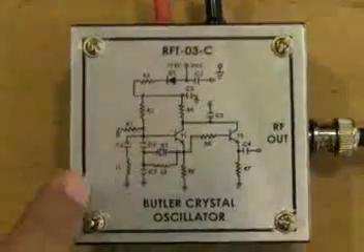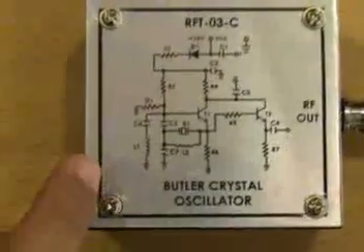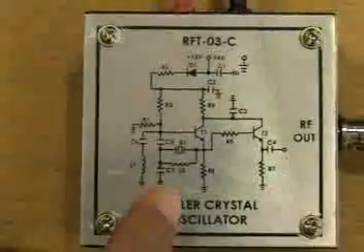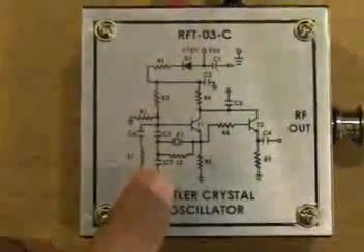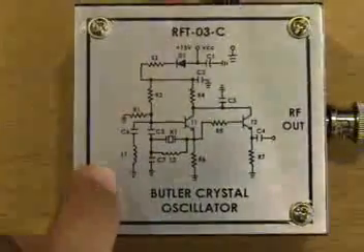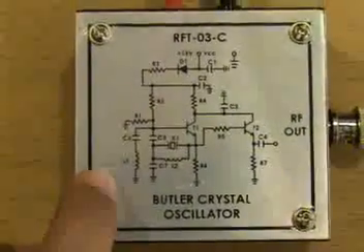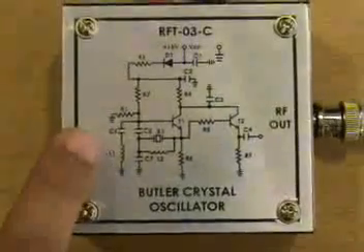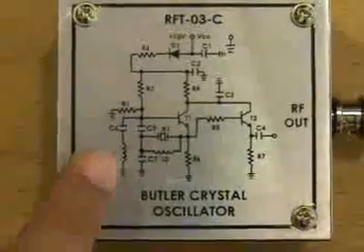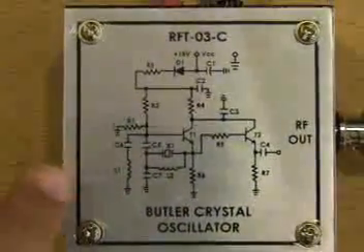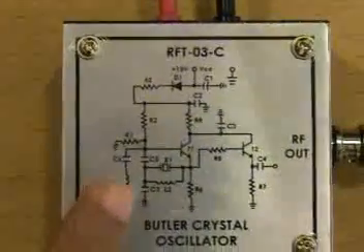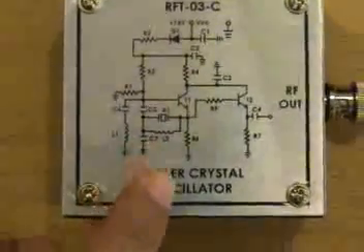We are using 2 coils in this Butler crystal oscillator. One of the coils, which is in parallel to the crystal, is used to suppress the fundamental mode of the crystal oscillator. The other coil, in function with its L1 and C6 components, forms a tuned circuit which tunes at a frequency roughly approximating the overtone frequency of the crystal.